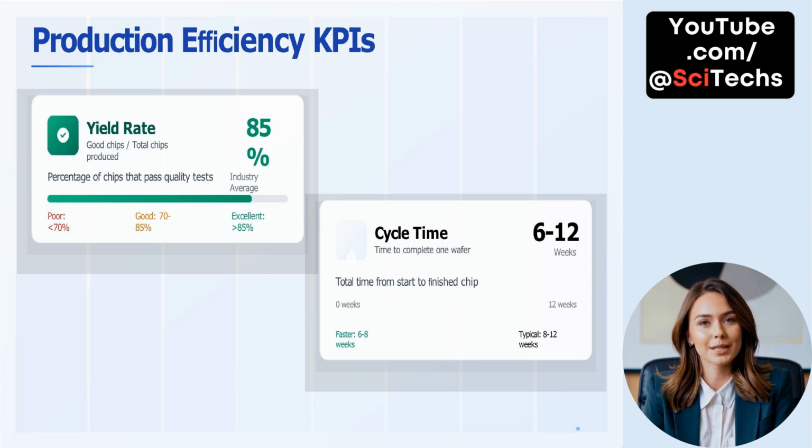Another essential KPI is cycle time, which tracks the total time needed to manufacture one wafer from start to finish. This includes all steps, from wafer prep to final testing. A faster cycle time is typically between 6 to 8 weeks, while most fabs operate within 8 to 12 weeks. Reducing cycle time and improving yield leads to higher throughput, better cost efficiency, and stronger competitive performance.